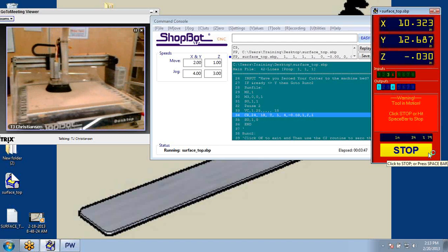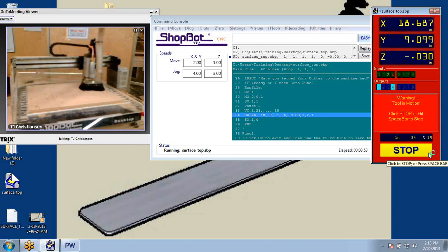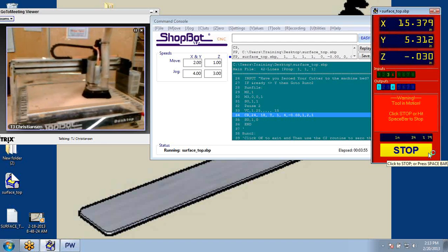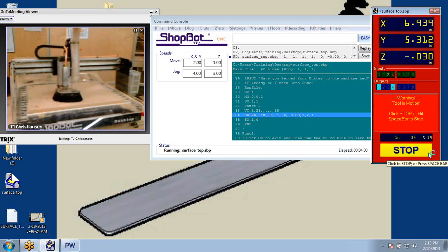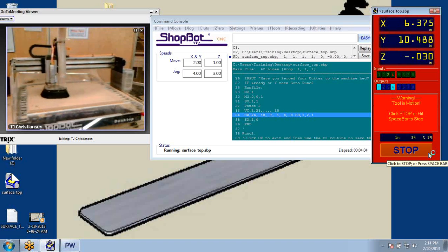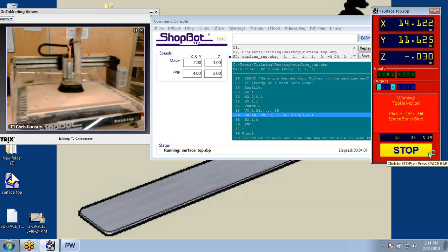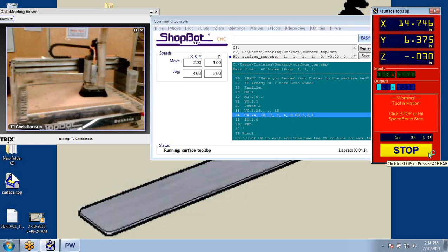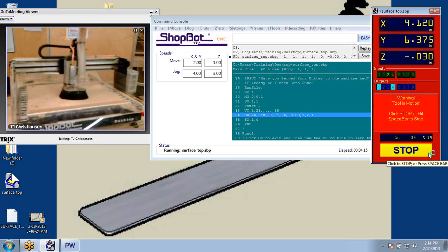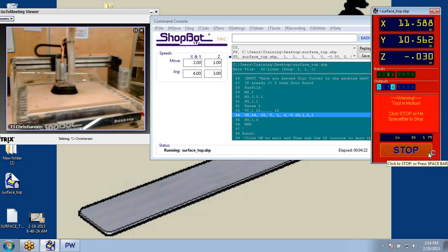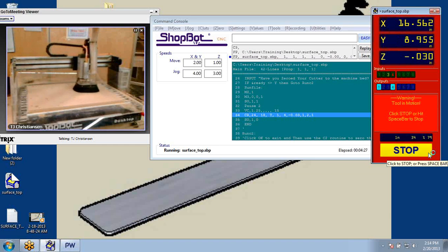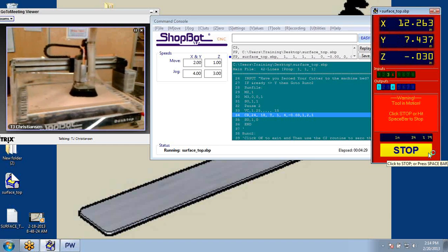A standard surfacing table surfacer, what we just did, it's gonna get the job done. It's not efficient, but it's just us on the weekend sort of thing, no big deal. But I do it enough on people's job sites that I had to create a file. So I actually went in and drew a Partworks file for a 4-foot by 8-foot, and I dialed it in, got the feeds and speeds revved up really fast, and had the direction of the cut changed, so it's less stops and moves like that. So you can write a file like that too, but this works just fine.